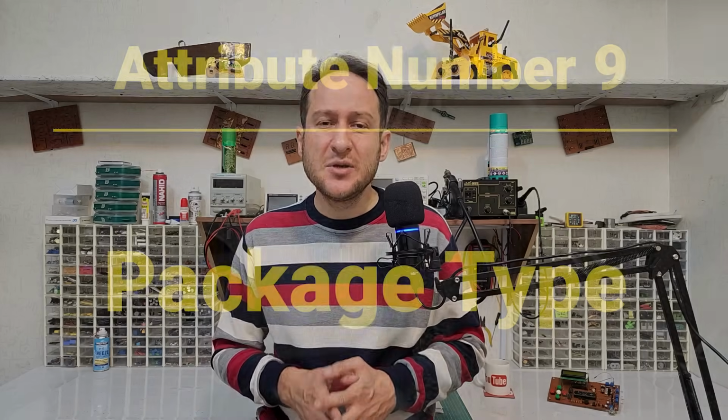or parameters that I will only introduce briefly. Attribute number 9, package type. Different voltage regulator ICs come in various physical packages. Some are small and surface mount, while others have larger through-hole pins for easier soldering. Consider the available space on your circuit board and your soldering skills while choosing a package type.